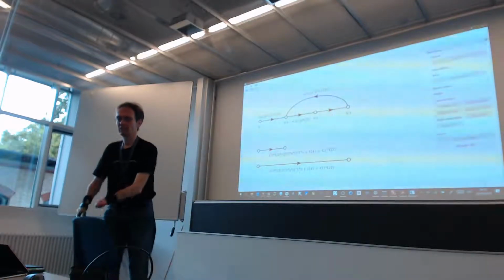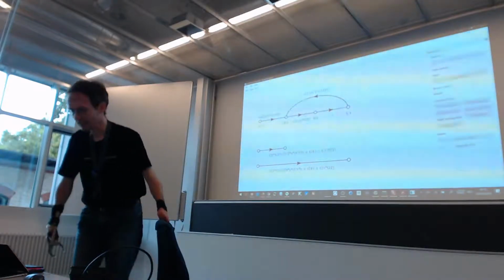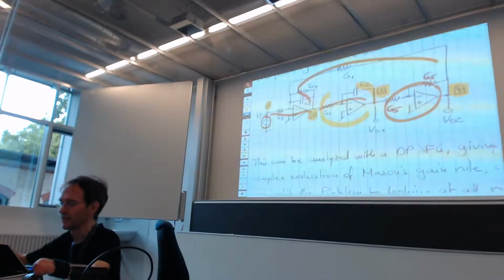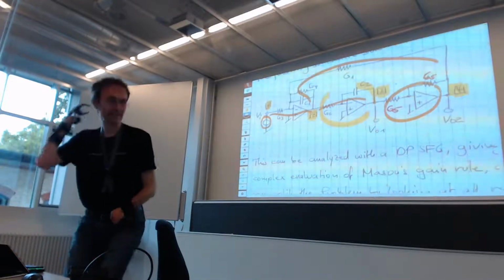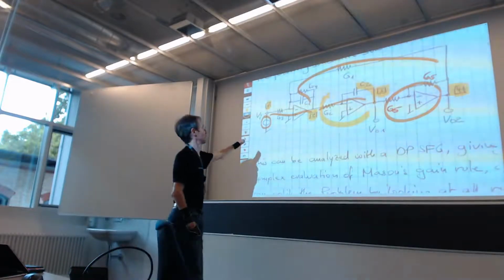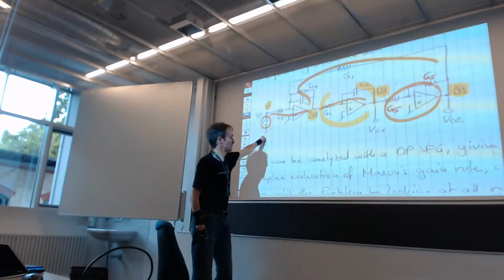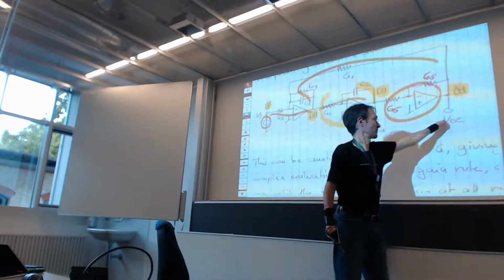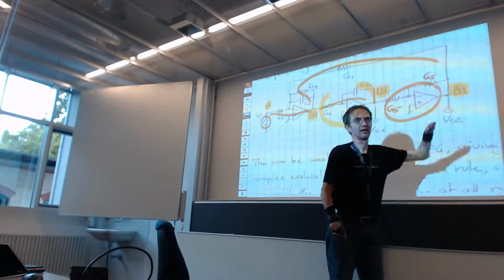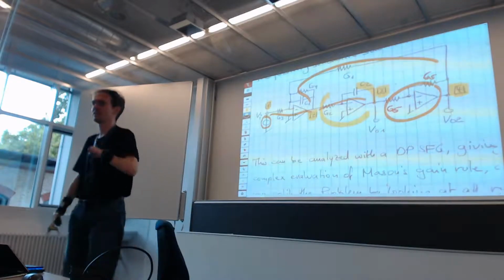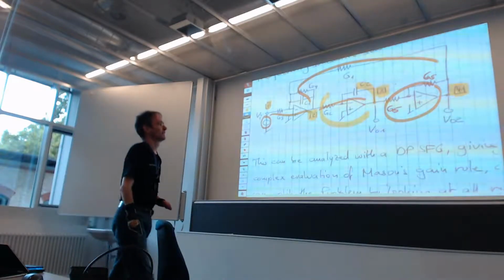And that is one of the nice things of this circuit, the Tau-Thomas biquad: if you build this and then go from the input to this output here, Vout1 or Vout2, it doesn't matter, these are both low-pass filters, but with a positive or negative sign.